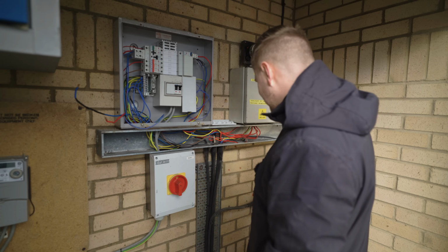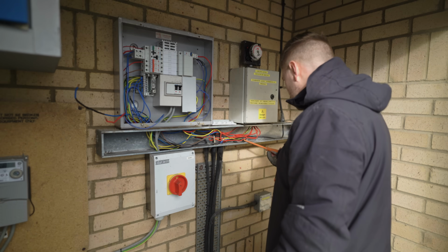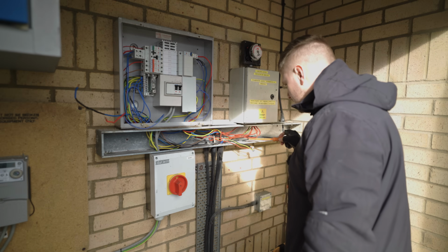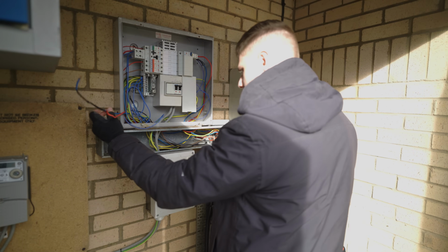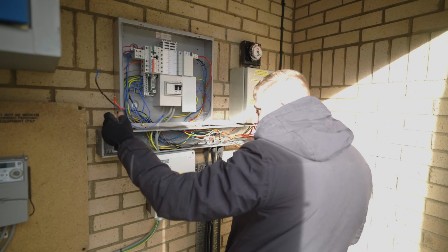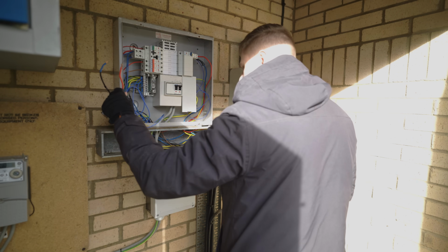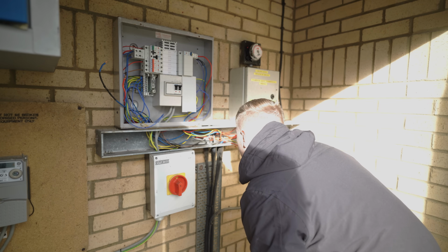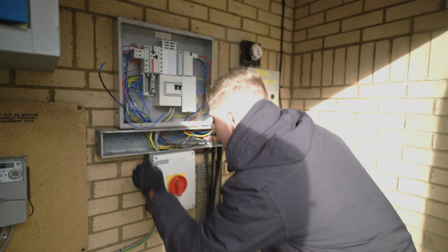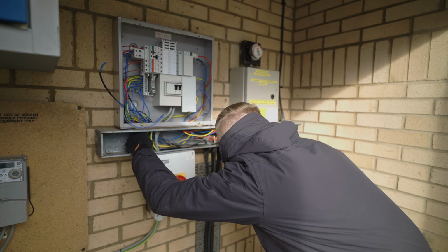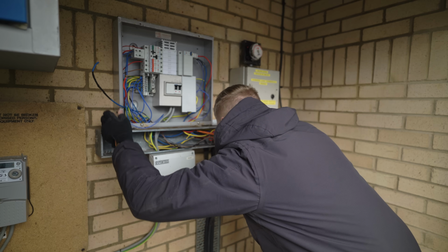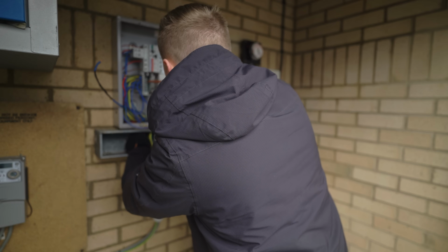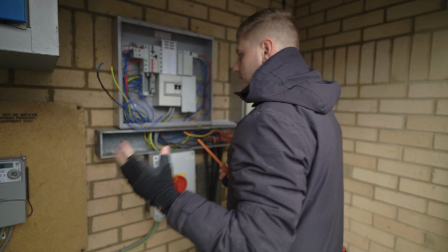Okay, there's a few things I can add to the report already. What we've got here is one circuit that's been shoved into some Wagos. Got some bunged holes here and stuff, so something's gone on there. Right, so that's that circuit. The live's obviously going to swing straight past and go into the contactor enclosure. That's fine. And then our earth is this one, I believe. No, there. That one gets traced, which is that one there. Cool. There we go. So we've got our circuit out.